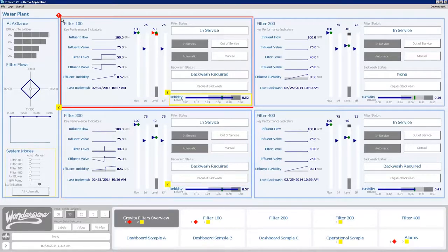So those techniques for the alarm borders make it easy to distinguish what's an alarm and what action needs to be taken. Another element that's being shown inside of this particular demo is something we've referred to as alarm aggregation. At each level within our system, from the individual variable, which is known as an attribute, to the equipment level, or what we call an object, or even multiple levels of equipment, or what we call areas, I'll be able to have numeric values of the distribution of the alarms by severity.